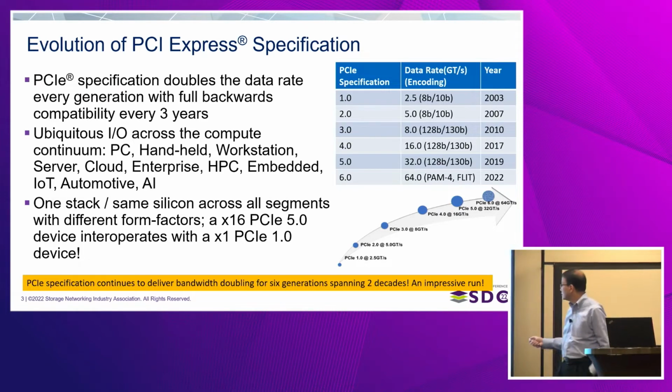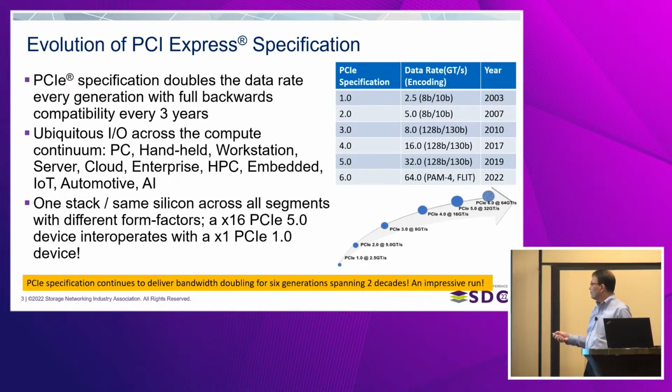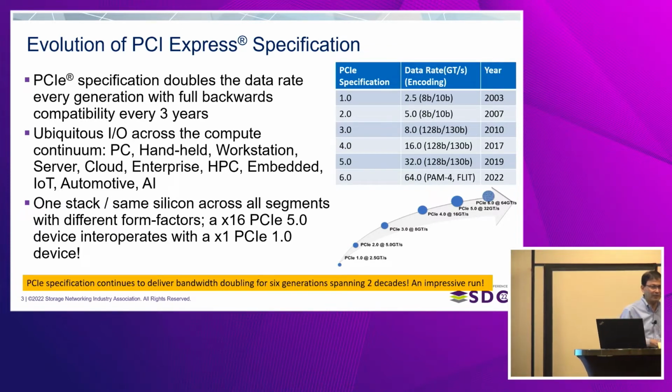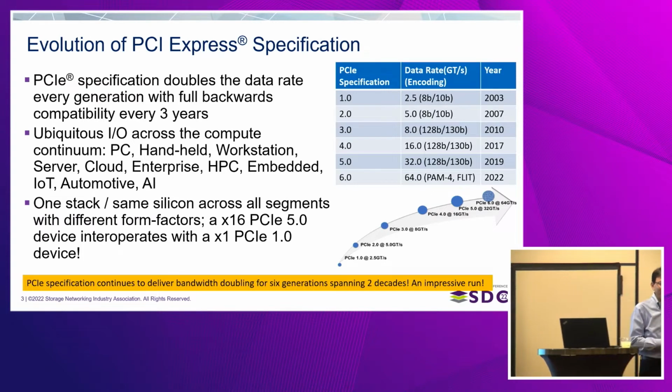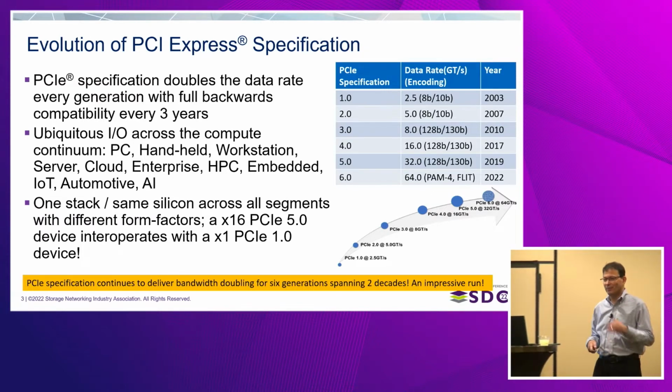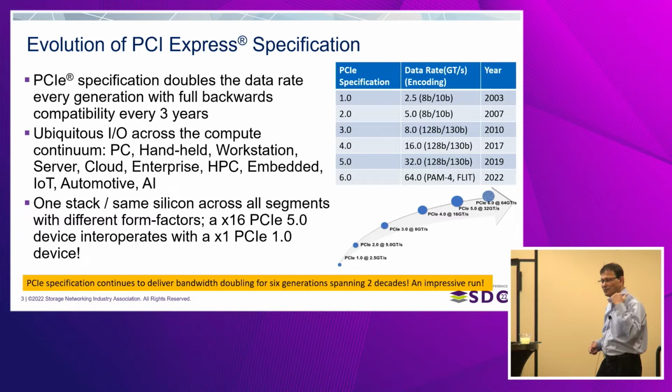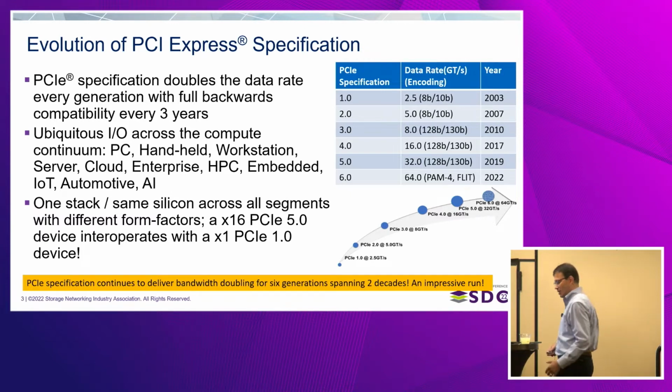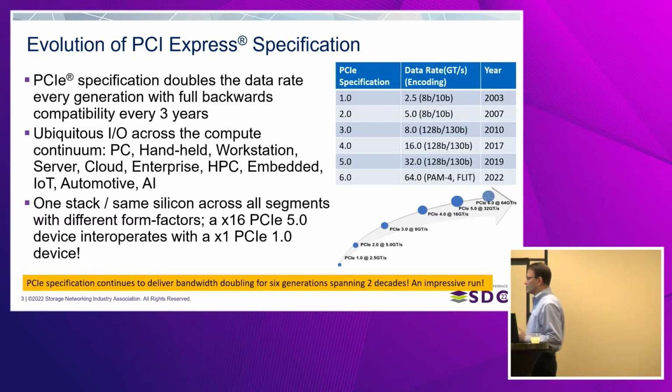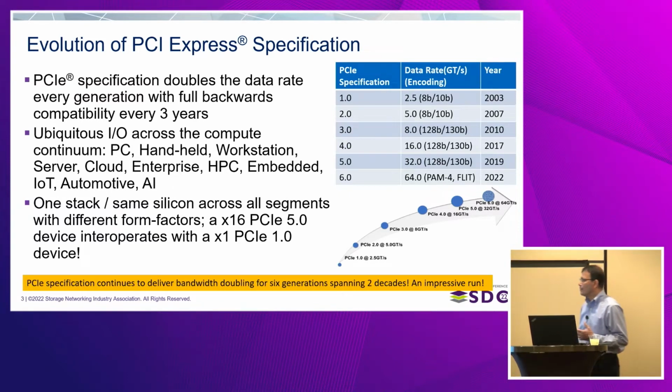So after that, you will see that the progression keeps going. 16 gig was the same 128b/130b, then 32 gig. If not, this would have been 10, 20, 40, and then 80, which would be getting harder and harder, right? So you probably had to do PAM4 back at 40, rather than we basically wait till it's absolutely necessary for us to make a huge transition. So this is a big transition, and we'll see why.